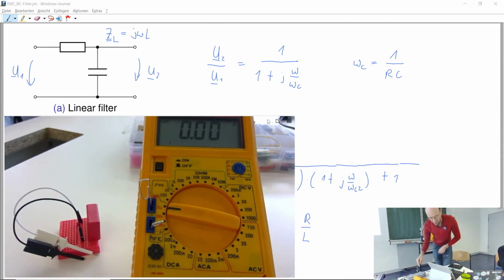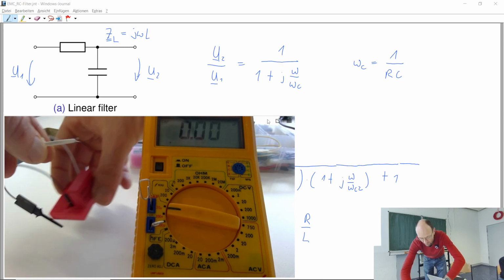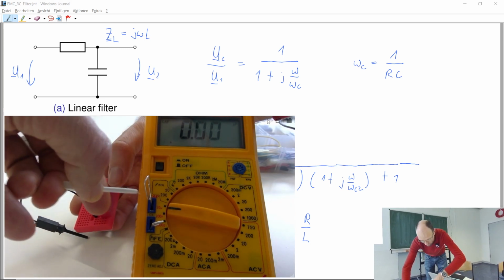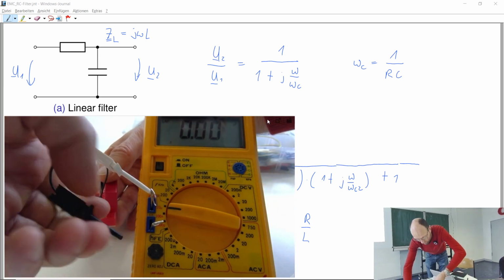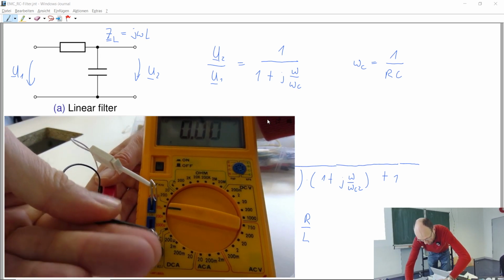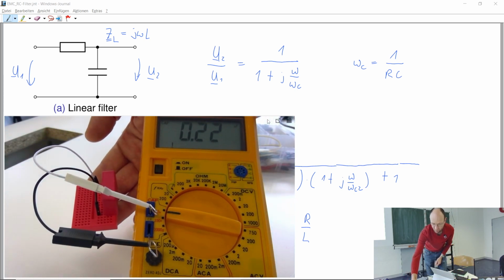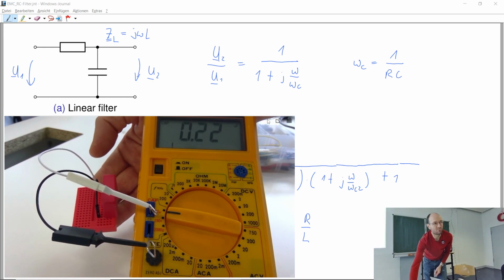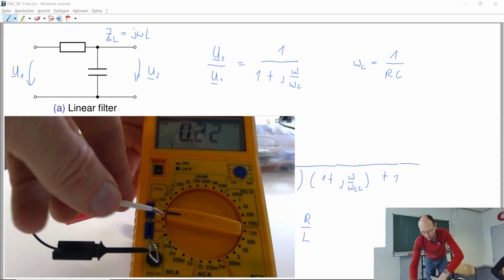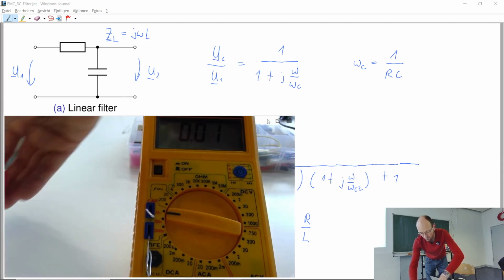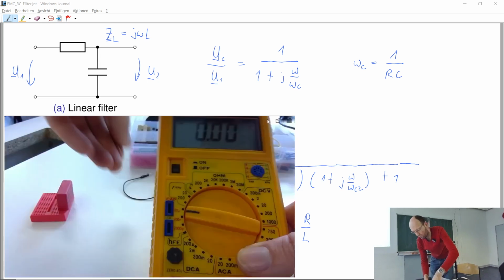And so now it's compensated, it's measuring nothing. And we can connect one clamp here and one clamp over there. And so then it's measuring, and it's measuring 0.22 microfarads. So this nicely fits. Okay, so we have a 0.22 microfarad capacitor. And I can remove these cables once again, and maybe also remove the paper clips.